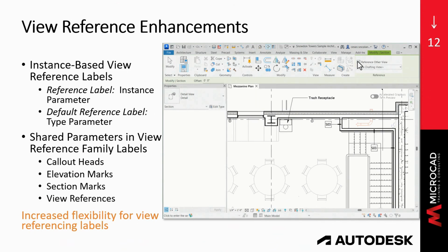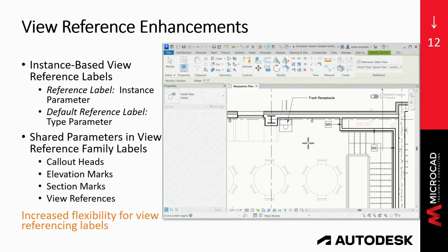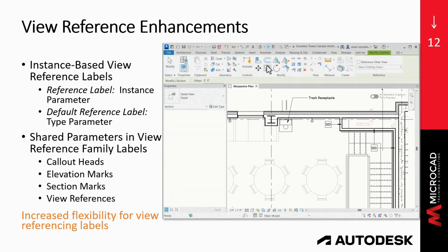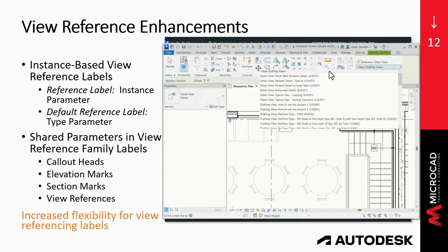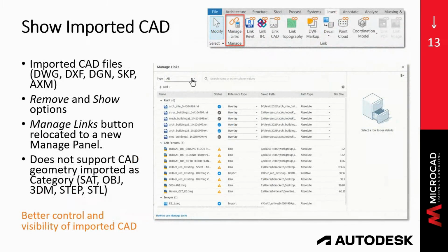But now, when you're creating a view reference, you have the possibility of adding a shared parameter, which you didn't have. I have a workaround of how to do it, but now you don't need to go beating around the bush to get it done. And to me, that is, again, huge enhancements, huge feature. Very happy about that. Moving on.